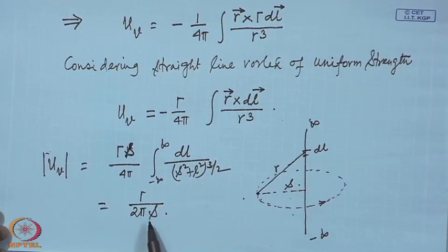could have been very easily obtained by the definition of that circulation. You apply that definition of circulation, what we wrote earlier, omega dot n dA equal to u dl or u dx. Use that, consider the curve to be a circle, and you can very easily get this relation straight away, that omega dot n dA is simply this gamma.